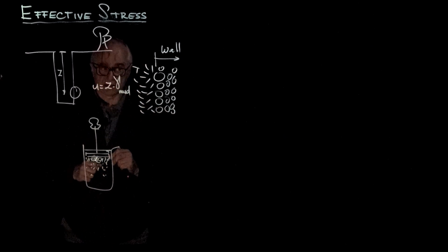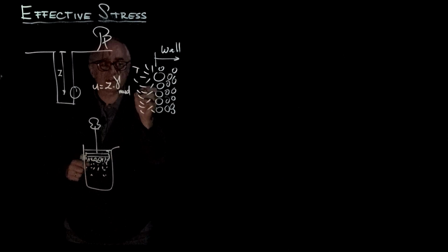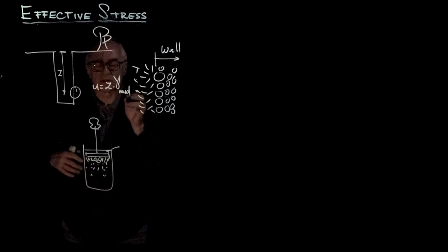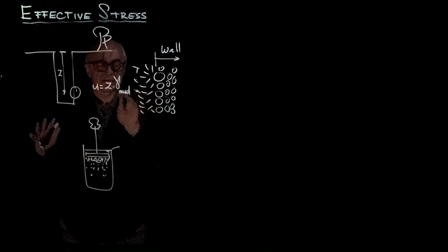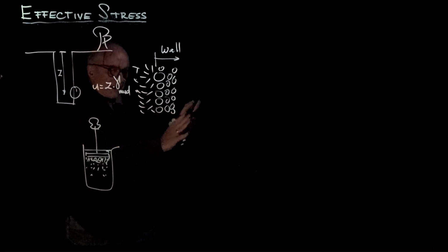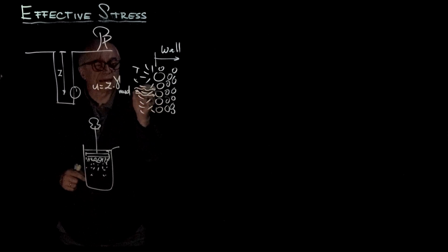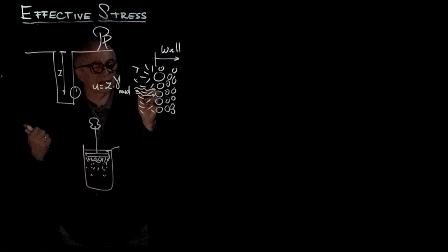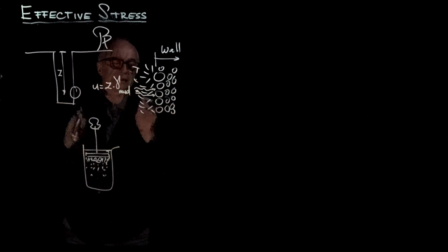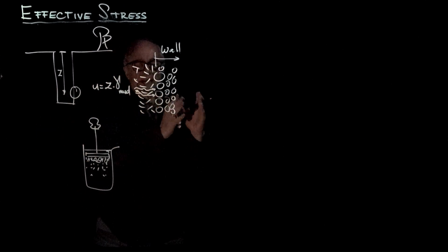So actually, what is happening is that each of these particles here has zero effective stress because nobody's touching it. But as they begin pushing against each other, this one is being dragged by the seepage, and that drag force pushes that one, and that one pushes against the next one, and the next one picks up the drag force plus the force coming from the neighbor to the left, and it begins building up, and the effective stress keeps increasing.